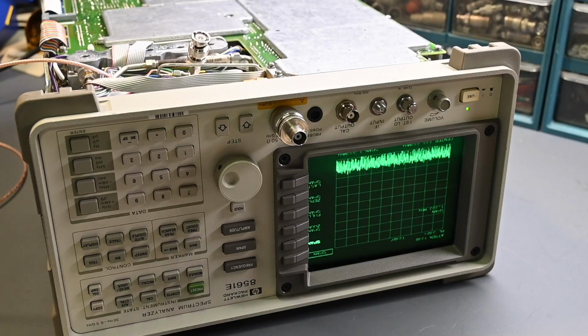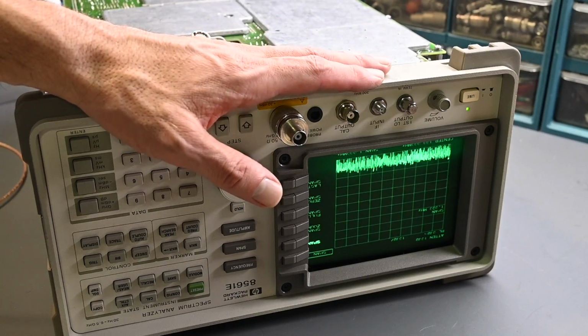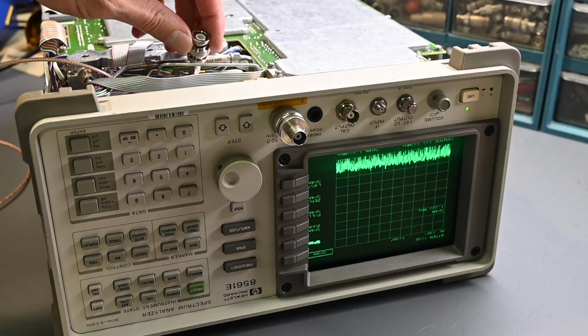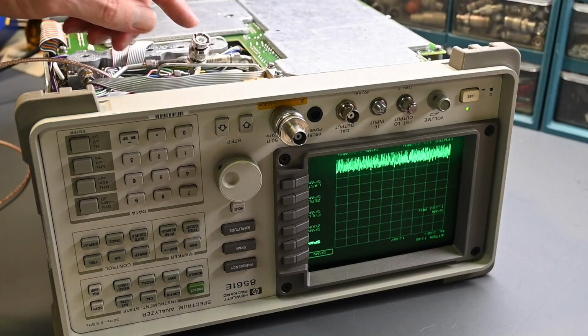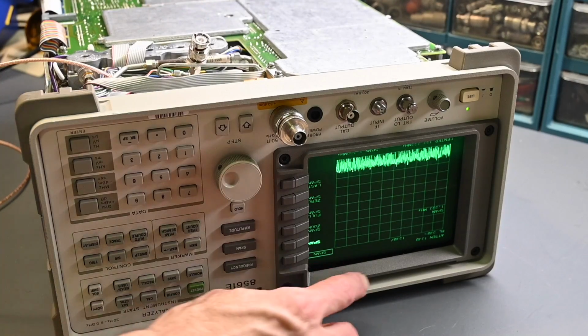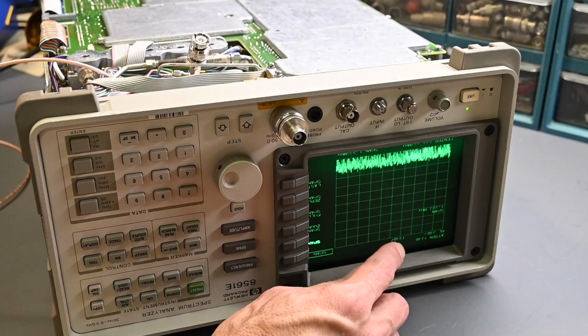Alright, so I have an idea for a test to see if the low band is functioning correctly in the spectrum analyzer after the switch and YIG-tune filter. So this is that RF adapter that I had installed on this rigid coax I said we'd get back to. My thought is that if I insert an RF signal at this point and we look at the displayed amplitude value at different frequencies, let's see if it remains constant.